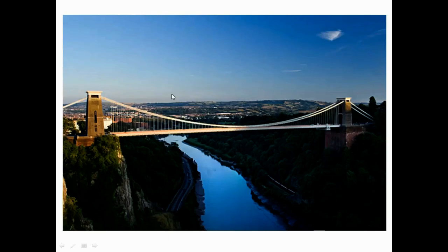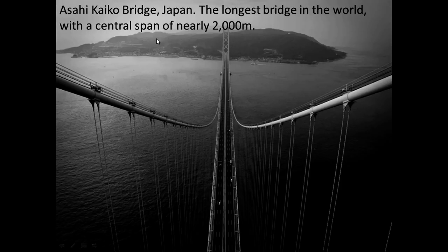Now there's a suspension bridge. This is Isambard Kingdom Brunel's, I think possibly the first ever suspension bridge, the Clifton Suspension Bridge across the Avon Gorge in Bristol. And what's happening here, well, you can see instead of the cables directly taking their load from the masts, from the uprights to the deck, here we're slinging a continuous line from one side to the other, and then the deck is being hung vertically off that, and that will give you an even longer span than the cable stay. It becomes even more efficient.